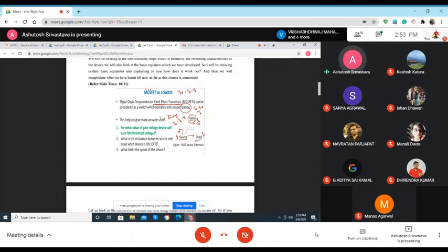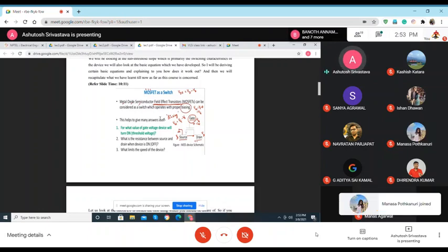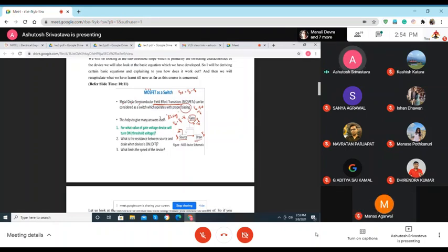So this depletion width is related to doping concentration, to drift and diffusion, and the built-in potential. The width of your depletion region can be changed, manipulated or guided by applying external bias.